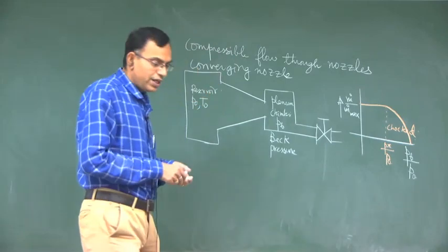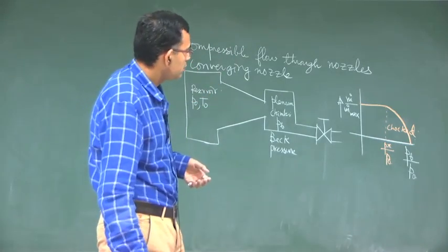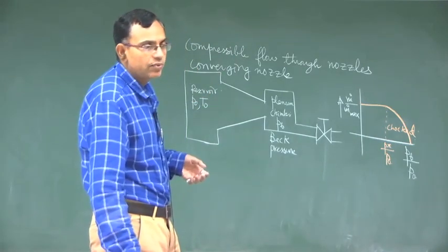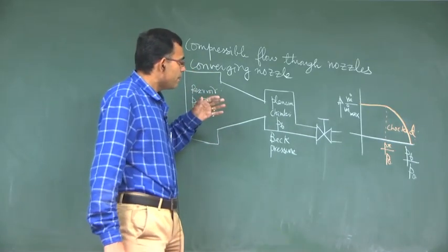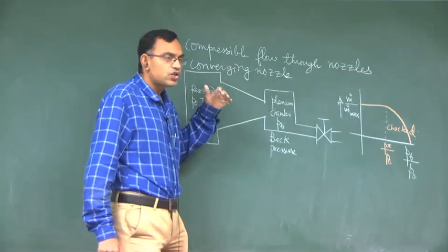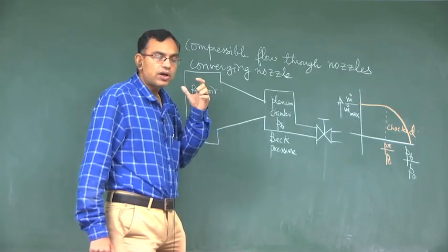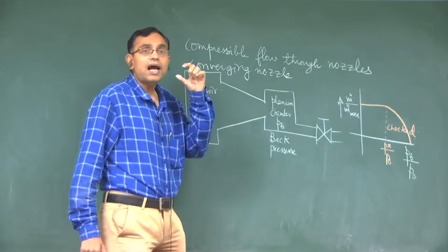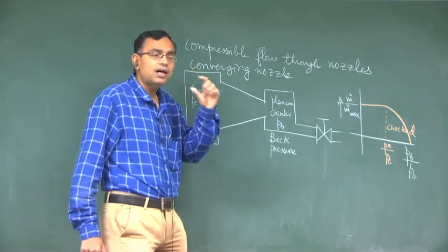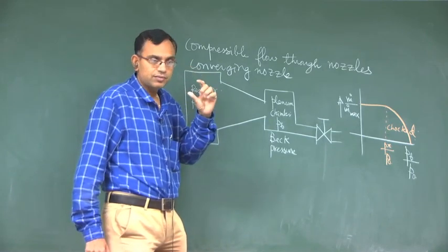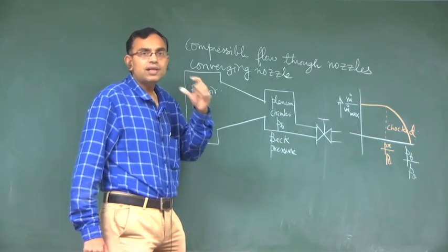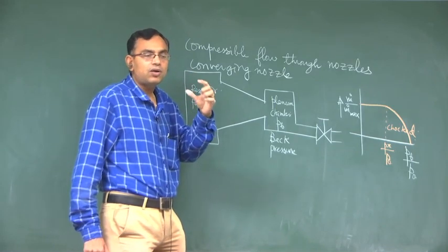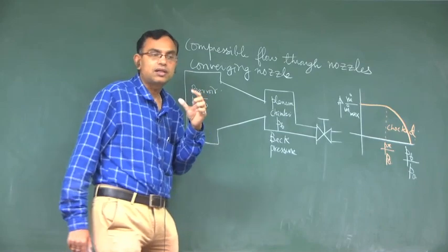When we were doing that, the conclusion that we arrived at is that the sonic condition, if it at all occurs, will occur at the minimum area location, but it is not always necessary that the minimum area location will have the sonic condition.